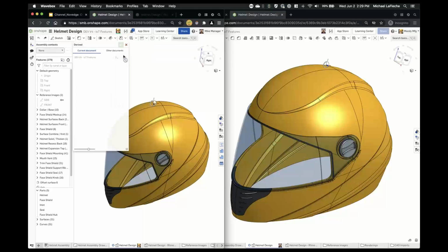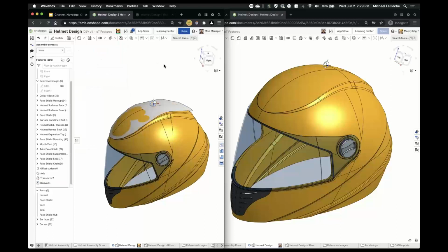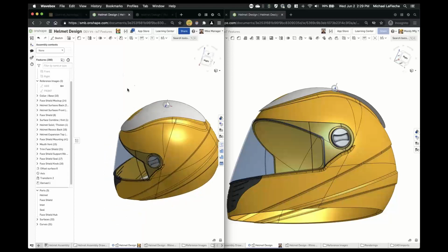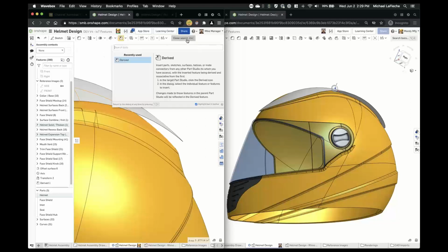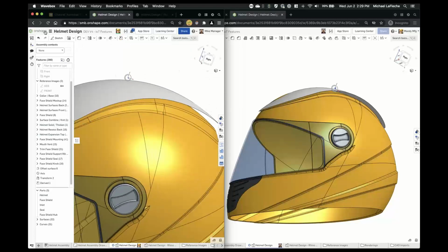I'll use this thing called a derive function. It's not important, the name of the function, but you can see I have that Rhino surface now that I can bring in and use in this design. And look what happened. It instantly updated for Mandy, who still had the document open, right? So we were able to take that Rhino surface, and now I could use it to extrude something, split with it, cut with it, do various things with it.